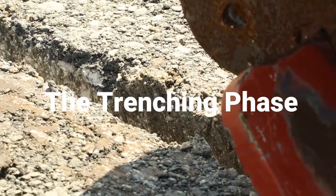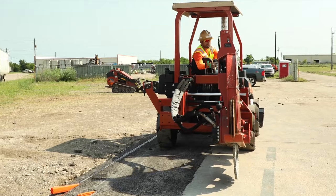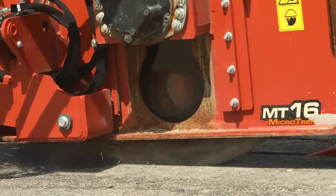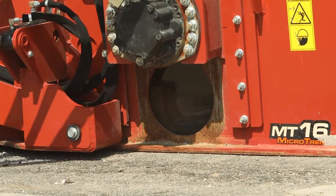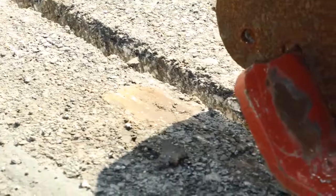Step 2. Trenching phase. Partner with a reputable equipment supplier and operator if you don't have specific experience with saw cuts or microtrenching. Cut the route to a predetermined depth and width according to approved plans. The proposed route should be carefully determined, avoiding utilities and obstacles that would require cutting the conduit, keeping the route as straight as possible.